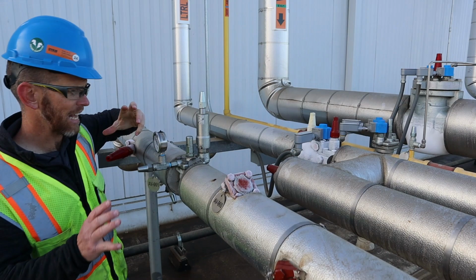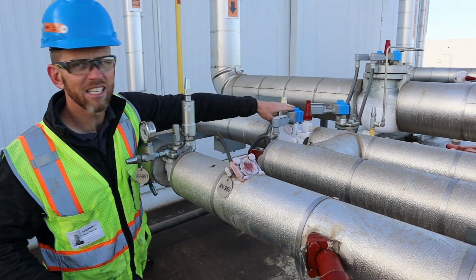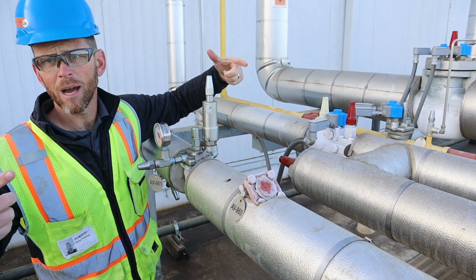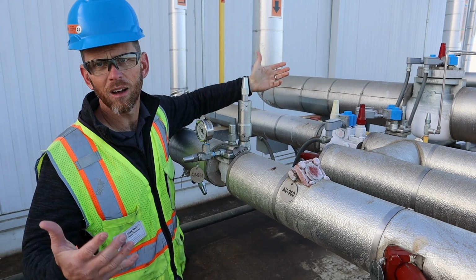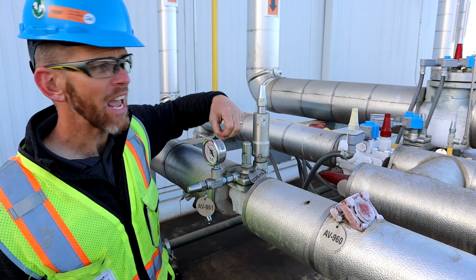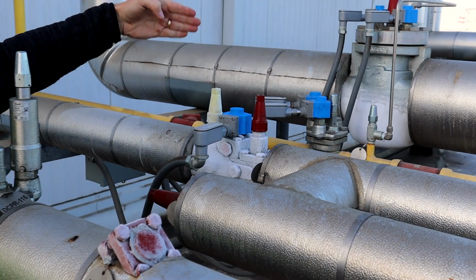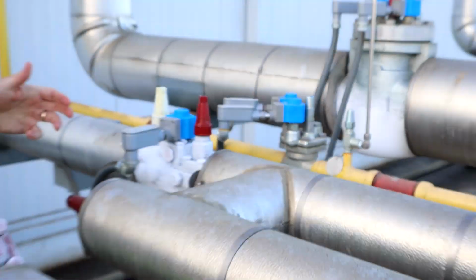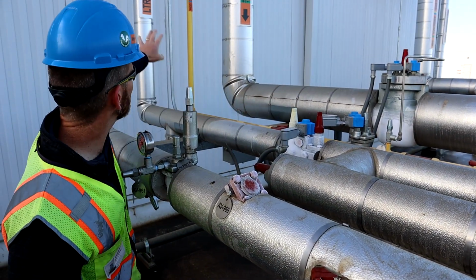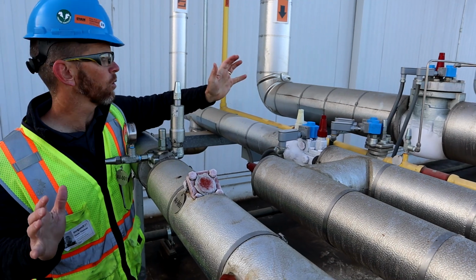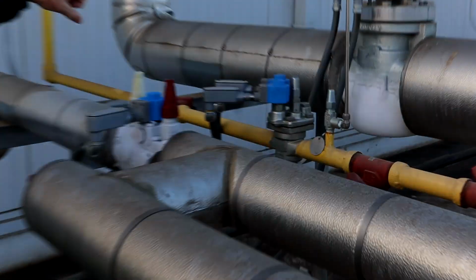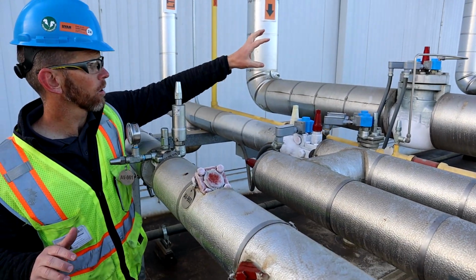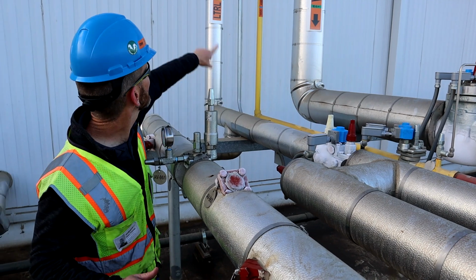When we go to hot gas defrost, the first thing that will happen is this valve will shut off. The fans turn on and continue to run while it goes through a pump down period of, let's say, 10 to 15 minutes, depending on the coil and how the system's set up. Then the hot gas solenoid is ready to activate. Again, this is a two-stage solenoid. The first stage, when it activates, only opens the valve about 10%. That might be called a preheat stage. We're letting some hot gas into the coil, but it's not at its full flow yet. At the same time, this suction stop valve, due to the gas getting added to it, will close. So it is no longer open, and there's no more gas passing through this way.